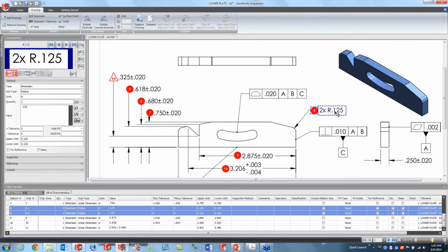And we might not need the tolerance per se when it comes to the creation of this file. But what we need to do with this is have something that's the variable for the inspector. So when they're using a mechanism like a pair of calipers to do this, there still has to be that upper and lower limits. Now if that had been preset in my template, then it would have automatically added those tolerances over here to these untoleranced values. With that, I can actually go ahead and recapture this if I'd like to, and just grab it out here from the screen one more time.